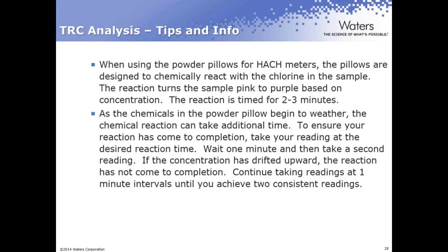One thing I want you to keep in mind when doing that, it's a very simple test to do. It's a very high quality test and will generally give you good results. But one thing to keep in mind is what you're doing is you're timing a chemical reaction. So as the chemicals in that powder pillow begin to weather over time, that chemical reaction can take a longer time to complete. So here's what I recommend you do. You want to make sure that the reaction has come to completion. So what you do, add your powder pillow, wait your 2 to 3 minutes, whatever your method tells you to do, and then take your reading at that desired reaction time.